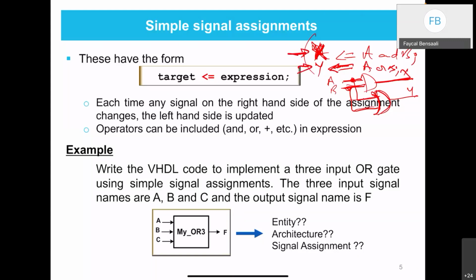And both of them will give me this circuit, and it doesn't matter which one I write first, yeah? And this is why we say concurrent. They run in parallel. I could have started with Y is equal A or B, and then I can write X is equal A and B. And this will give me exactly the same circuit as the top one.